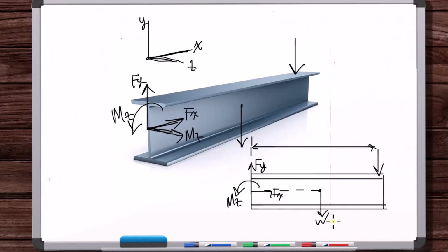Okay, now, when we made a cut like this, and we put these forces, these are called internal forces. Why are they called internal forces? Well, you can think about it. One reason is, what you do in mechanics of materials is you make cuts like that in pieces. You solve for these forces, in these pressure distributions. And so you're analyzing the forces internal to the member, right? What's going on inside? You call it stresses, the force per unit area, the stresses and the strains, the deformations inside of the material, internal to the material.